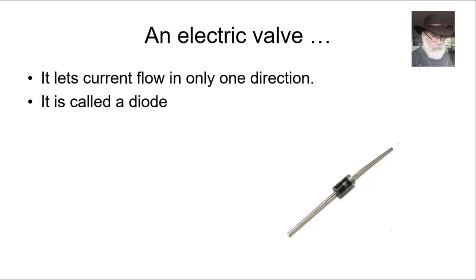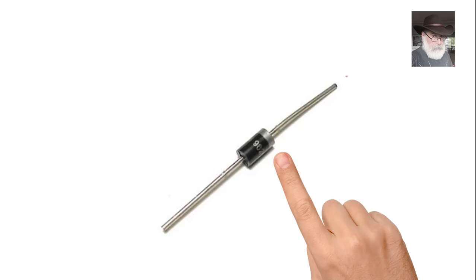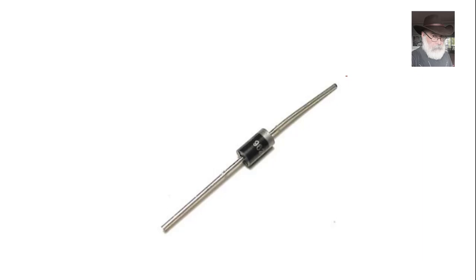Here's a picture of the rectifying diode that you will use more often in this course. It is in your toolkit. There you identify with a silver band the so-called cathode of the diode. Yes, the 2 terminals of the diode are not interchangeable. One is the A terminal, the other is the C terminal, also labeled as the K terminal. One is the anode, the other is the cathode, which also are names that make reference to the original vacuum tube, but we continue to use them.